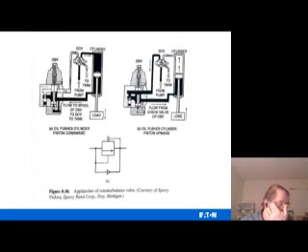Okay, here we have it. There's your symbol. Essentially that's your directional control valve, and it is blocked out with that, and there's the flow to the spool. This is your actuator or your load. Okay, and you're trying to keep this piston from falling down. So the counterbalance valve keeps it in a static pressure, so you don't have the pump holding it, putting pressure on it all the time.